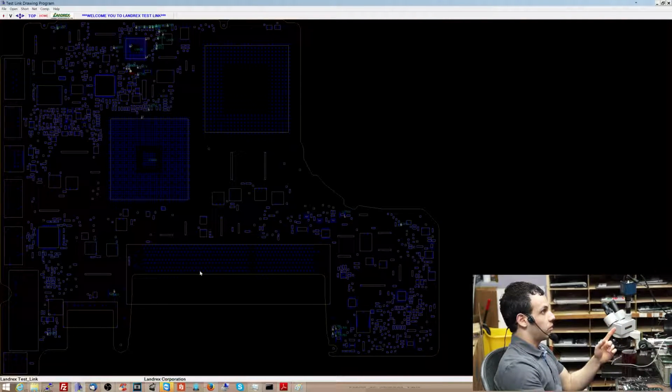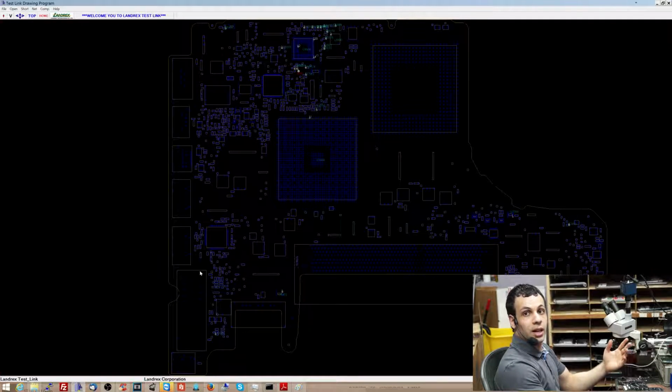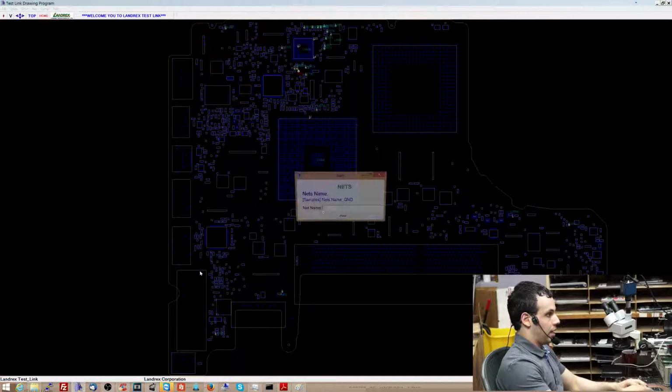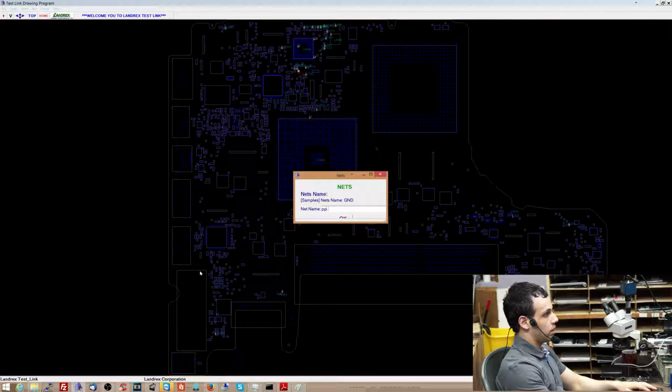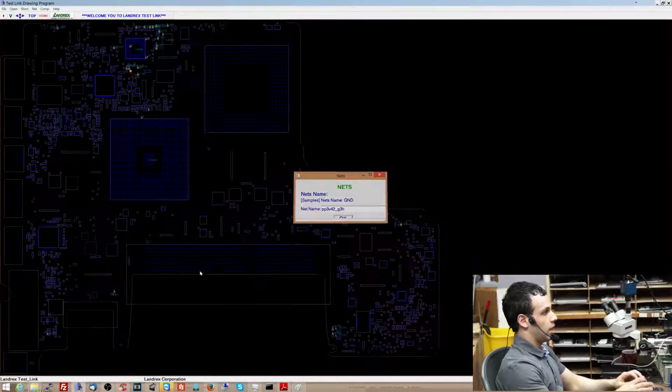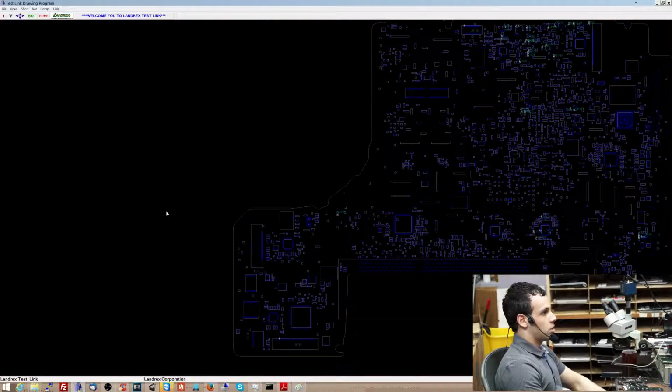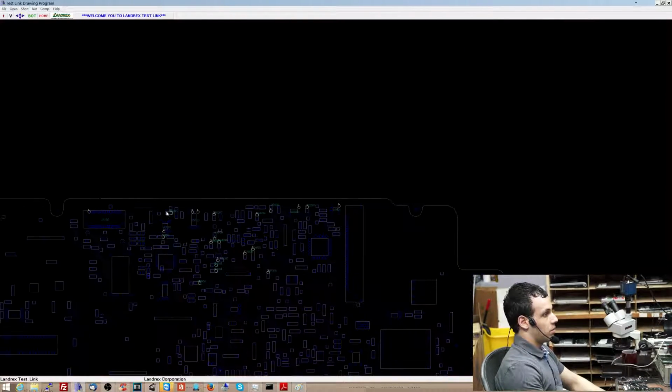So I went into this board view program, which you're probably going to ask me where I got it, even though the website is on the screen in the back of every single PDF for the last 2 years of this video series. I hit N, I put PP3V42_G3H, hit enter, and now it shows me everywhere in the board that that is supposed to show up.